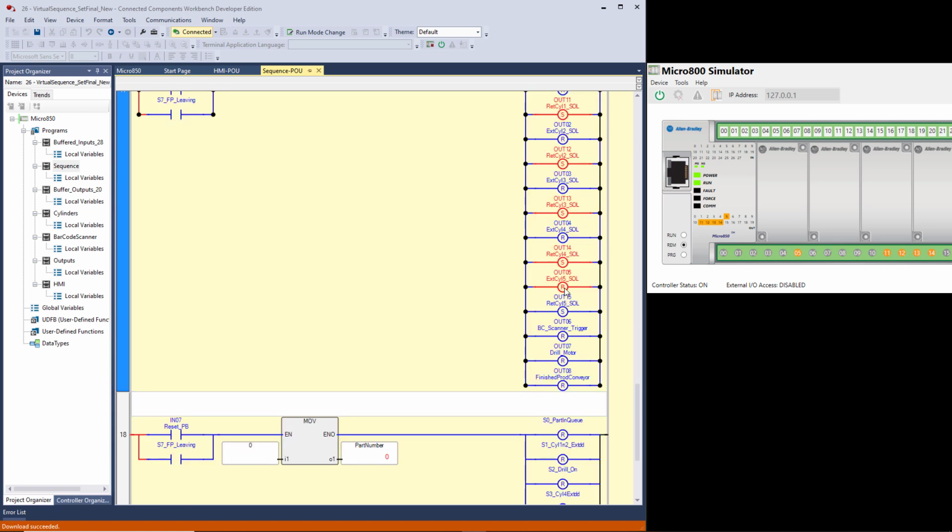Extend cylinder 5 solenoid. That's a cylinder that we don't use very much. It's all the way at the end of the process, and we could actually live without it. It's a stop that extends out onto the finished product conveyor to prevent any product from going on out of the cell downstream. Primarily it's there at the behest of the downstream station that wants some control over whether or not product can come down that conveyor. So this prevents it entirely.